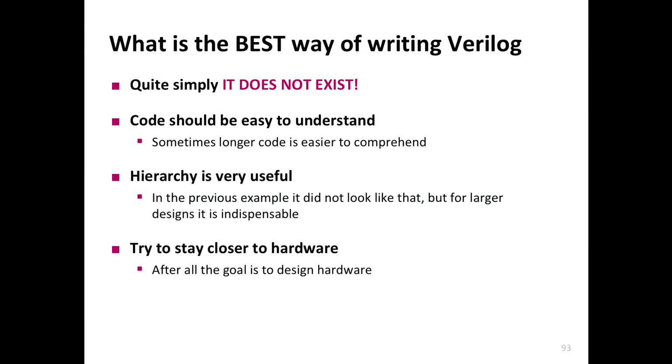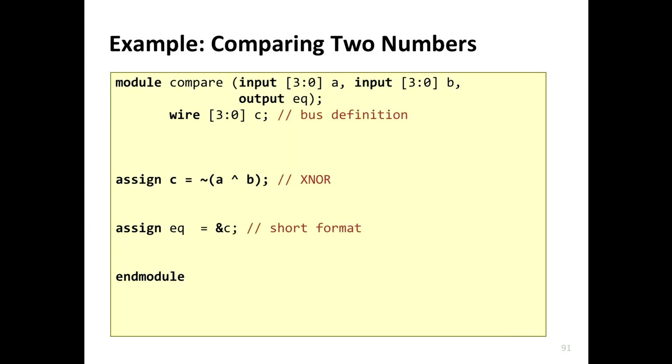It's very difficult. Something that I did not say right at the beginning: the main difference between C and Verilog is parallel execution. Whatever code you see, especially in the combinational circuit part, does not execute one after the other. It's hardware, and hardware is typically parallel. So all of them execute at the same time. What do I even mean by that?